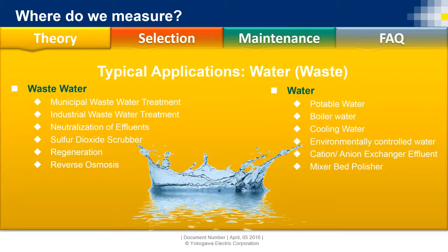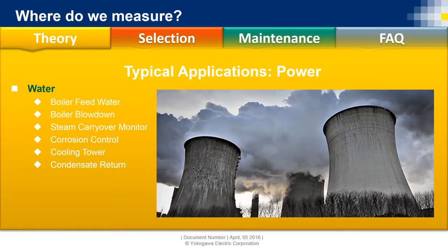You will have one pH coming off of a line, but then you're going to have what we call specific conductivity. Then that sample will run through a cation resin bed, a cation bed on your panel probably. After that resin bed, you'll have what's called cation conductivity, and then that sample may go through a reboiler, and you'll have what's called degas conductivity. So you have 3 conductivity measurements for the most part to your 1 pH. So you have more, you just don't have to maintain them as frequently.